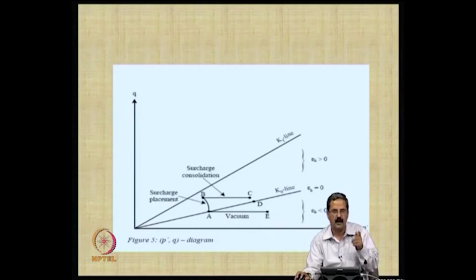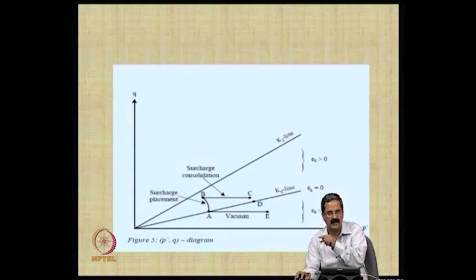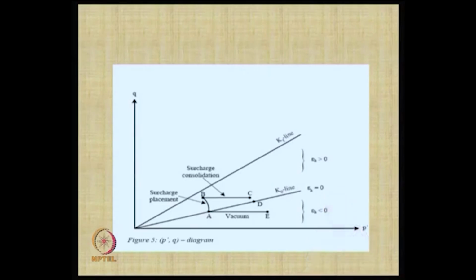So, for example, pore pressure is generated, you say sigma dash equals total stress minus pore pressure, minus this plus, actually this becomes additional. So, the effective stress will increase because it is the opposite, it is a suction, it creates a suction. So, in the process the total effective stress is increased: effective stress equals total stress minus pore pressure plus suction.